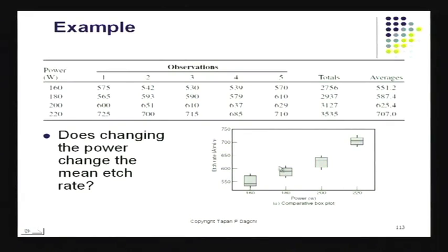If you see it another way, that etching actually is showing up as a little band here at 160. Notice here, there is of course a mean value there, but there is a band. There is a variation there. There is of course a band of variation in response. There is a band at 180, a band at 200, a band at 220. These bands are variances that have been caused because all the different noise factors also changed while I was replicating my experiment. So because of that, I end up with these little bands in all these 4 settings.